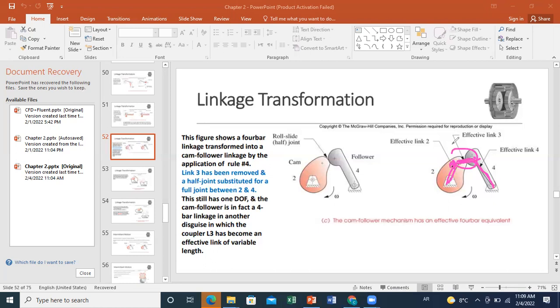So the idea is, let me observe one line of the cam, and let me observe one line of the follower, and I can identify for each angle of the cam a certain position for the line of the follower, and then for each instant I can draw the contact line. And because the profile of the cam is varying, the contact line direction will vary, and also the distance between the 2 intersection points with the line of cam and follower will be different.